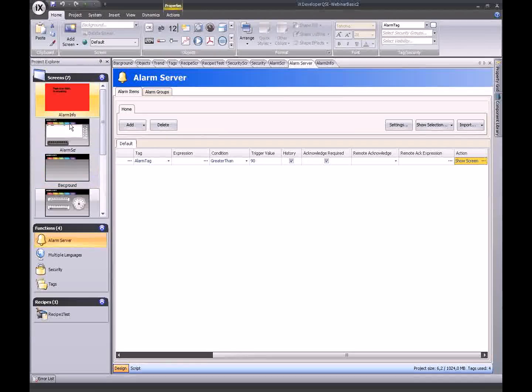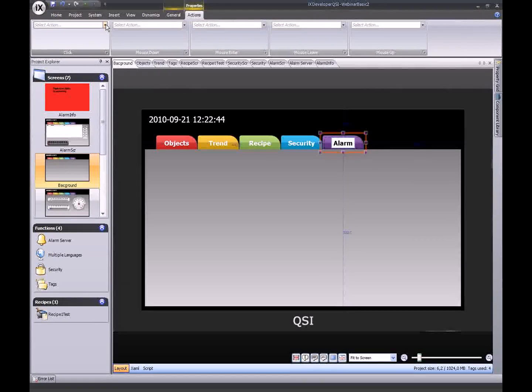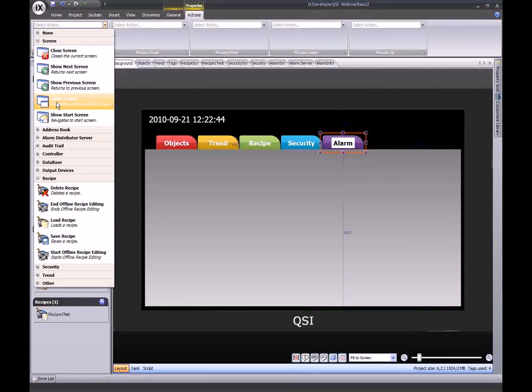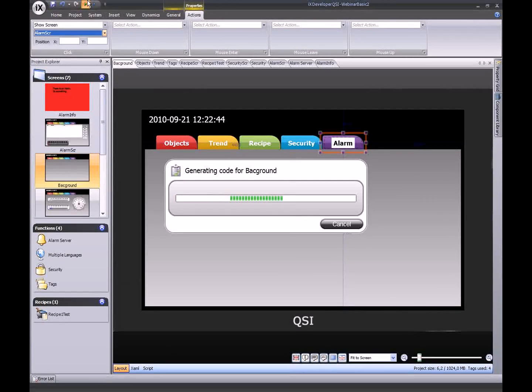Let's hit OK. And for the final time, we go to the background screen. And we call it alarm. And have an action on it. Show the alarm info screen. No, sorry, the alarm screen. So let's compile for the last time. And I will head off into the conclusion and question part of the webinar.